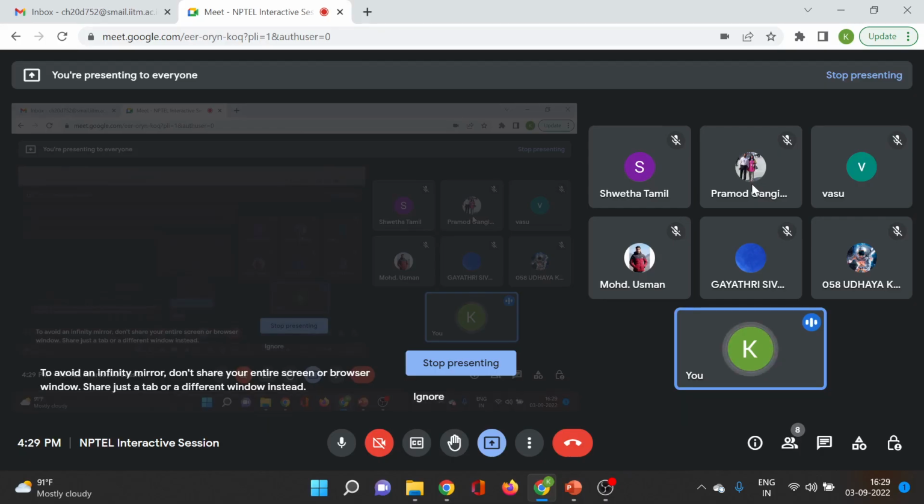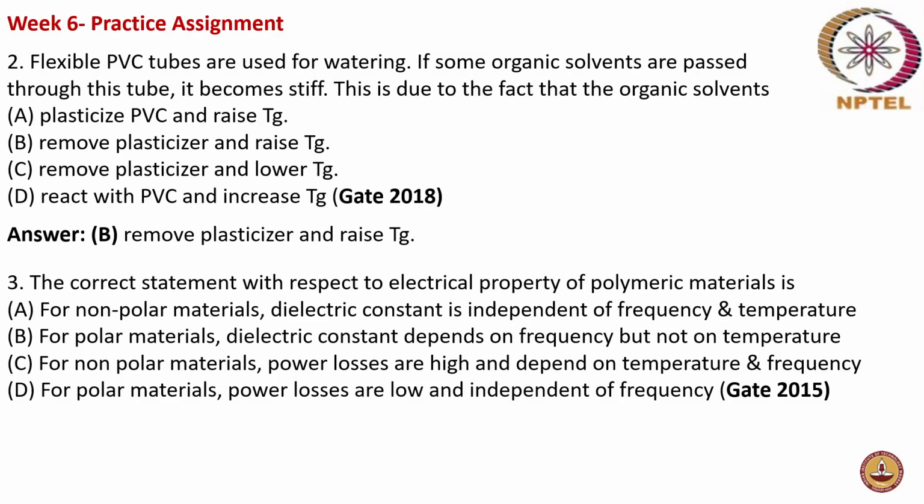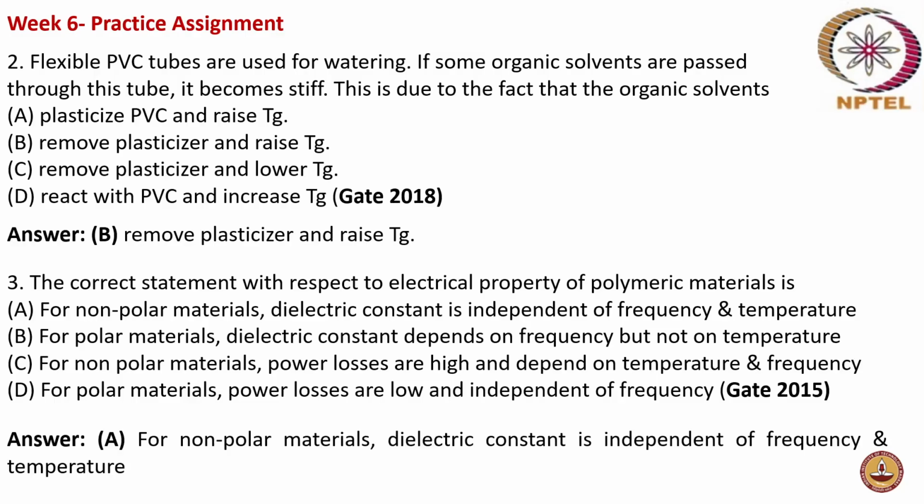Vasu answered it, is it? Yes, ma'am. Okay. Anybody else? Shweta, what is your thought? Uday Kumar, Mohammed. Yes, ma'am. I agree with you. Okay, what you said is right. So for non-polar materials, your dielectric constant is independent of frequency and temperature, because you will have some residual or very minimal dielectric constant, and it really doesn't depend on frequency and temperature because the material cannot be polarized, as you said.